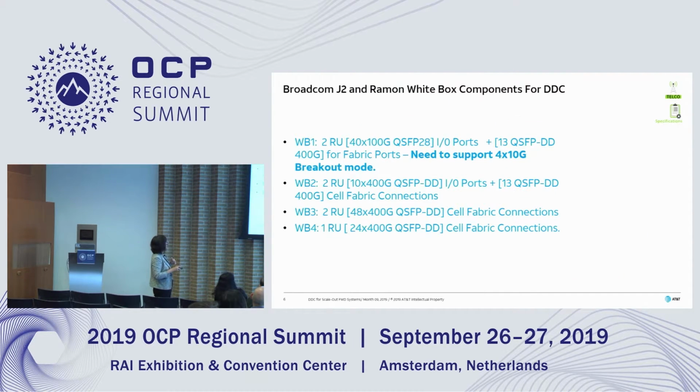Oh, and then the other thing that I want to point out is that we also need to support the breakout mode, because all of this is brought out as 100 gig ports, but we do want to support some of the 10 gig ports so that we can have backward compatibility for other systems. So in the spec, at least for our application, we see that it would be a good advantage to have the breakout. So in the design, we need to do that.